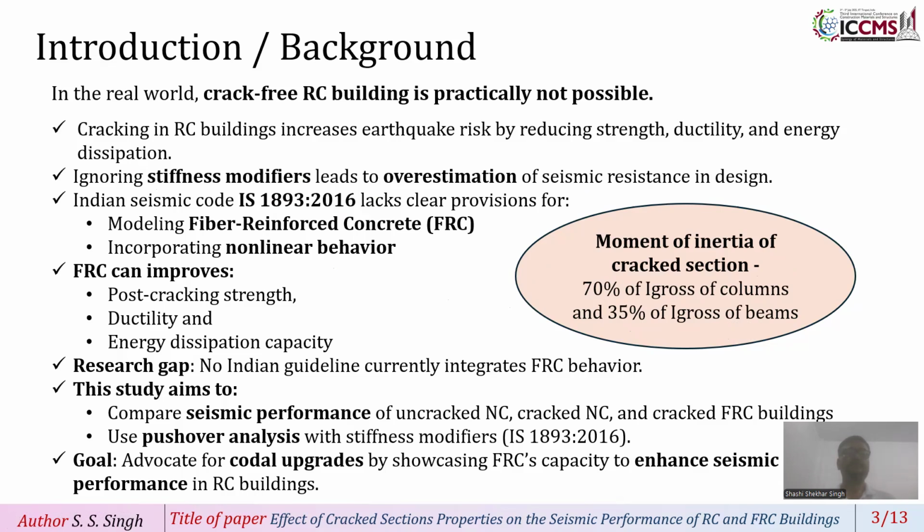Also, the Indian seismic code IS 1893 lacks clear provision for modeling FRC and also incorporating nonlinear behavior. And what can FRC do? FRC usually improves the post-cracking strength, ductility, and the energy dissipation capacity. In the next slide, we will see in more detail why FRC has been considered.